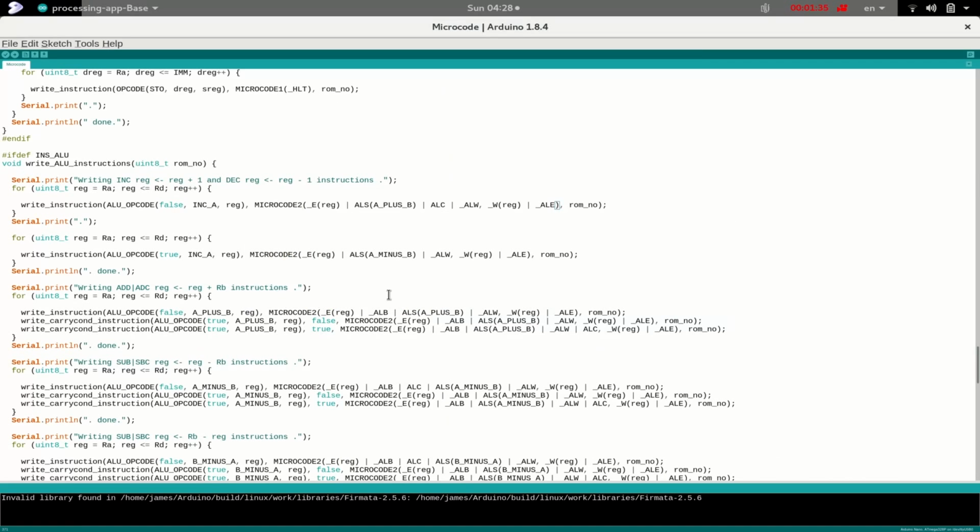So that should be exactly what this first microcode does for the increase instruction. So we're setting the carry, but we're not setting the ALU B signal, and we're setting the S signals to correspond to this A plus B operation. And then in the second byte, as we discussed, we'll be taking the results which we wrote into that ALU and writing into the register.